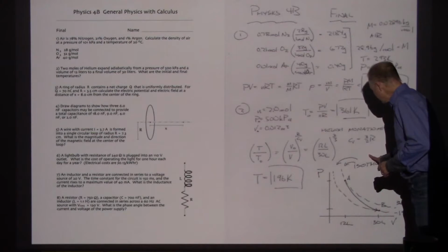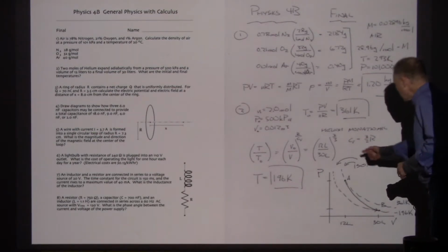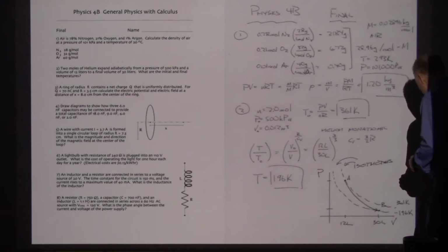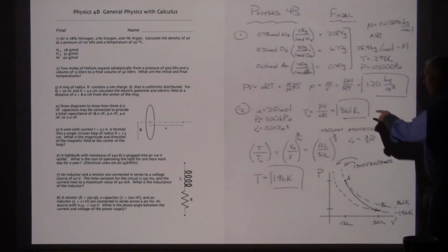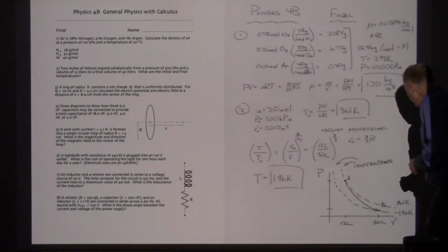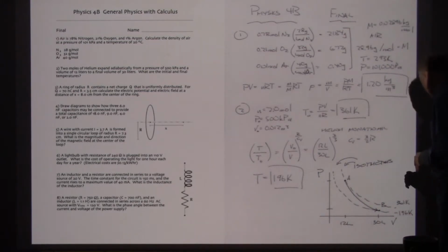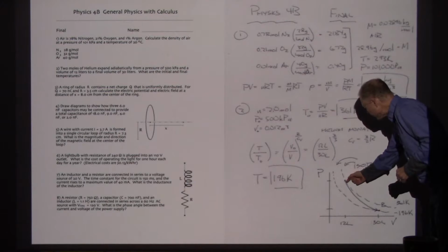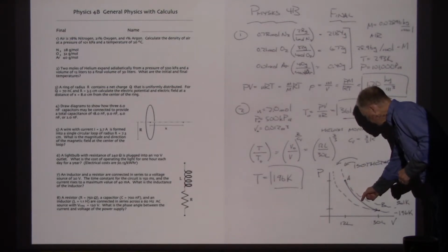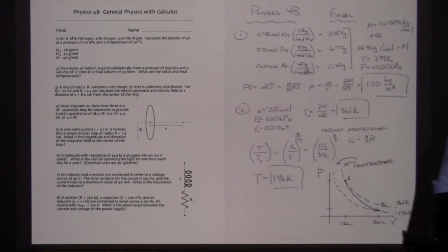So here is the PV diagram for this setup. And what I've placed in here is a couple of isotherms. Using the ideal gas formula, I've written in a couple of isotherms. One of those isotherms is representing the starting temperature, 361 kelvins. And the other isotherm is representing 196. These aren't minus signs here, these are just part of the isotherms. So 361 kelvins, 196 kelvins, and an adiabat would take us along a smooth curve that gradually drops through a series of isotherms.